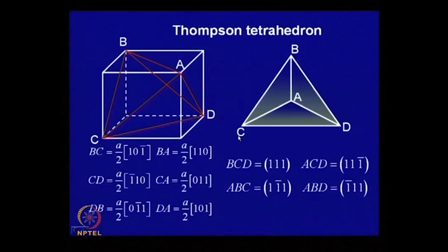Now, we have just seen how when one dislocation meets another, they interact with each other, and a very large number of such interactions are possible. We looked at a few of these. We looked at the formation of a Lomer lock, and when these Lomer locks are associated with stable stacking faults, the lock is much more stable, and this type of lock is known as a Cottrell-Lomer lock. So, this is one kind of interaction.